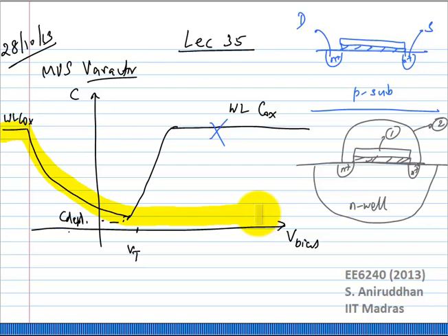Okay, it really depends on which. Many of these modern pure CMOS processes may not have a PN junction diode dedicated for this. You may be much better off just using the MOS varactor. However, there are cases where the MOS varactor may not have enough Q, or rather you can get a PN junction with a better Q than a MOS varactor. Maybe a lower Cmax by Cmin but a better Q. That is also possible. So you will obviously have to evaluate specifically for your case which works best.